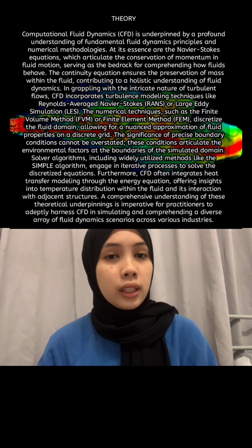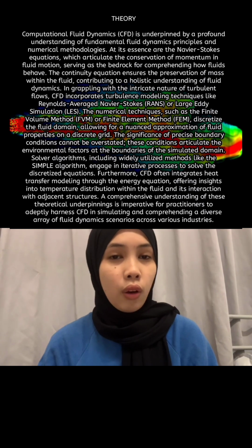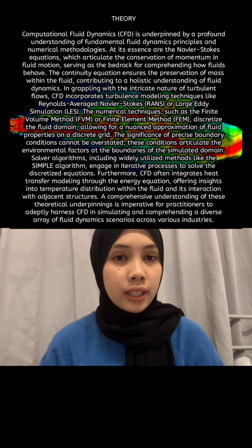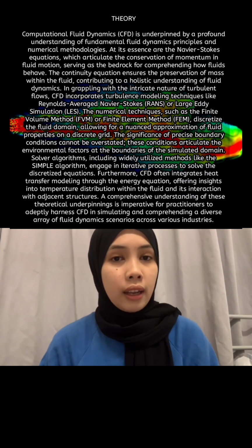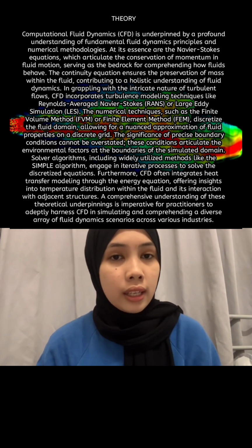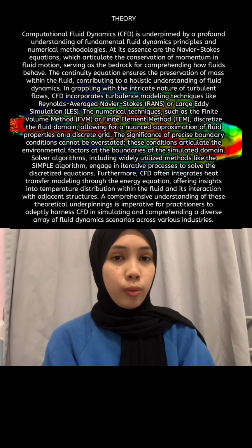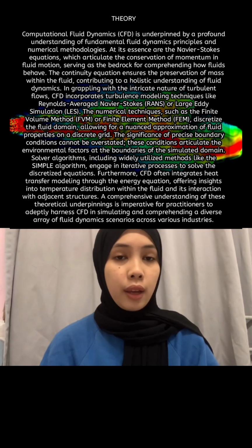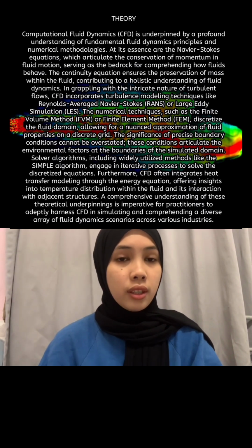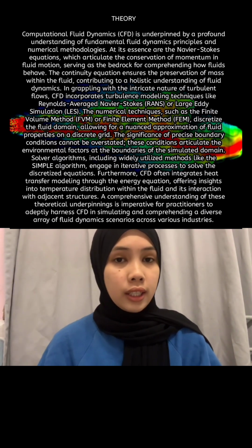In grappling with the intricate nature of turbulent flow, CFD incorporates turbulence modeling techniques like Reynolds-averaged Navier-Stokes (RANS) or large eddy simulation (LES). Numerical techniques such as the finite volume method (FVM) or finite element method (FEM) discretize the fluid domain, allowing for nuanced approximations of fluid properties on a discrete grid.